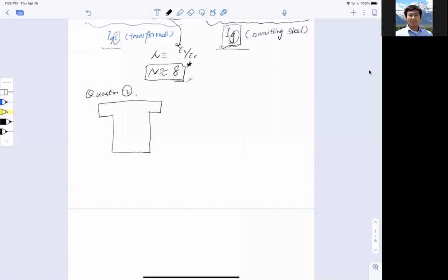So if I want to find out I_cr positive, how do I do that? When you're trying to find I_cr positive and you have steel reinforcement, first of all you have to convert that steel reinforcement into concrete. And knowing that the bottom part is cracked, the neutral axis is somewhere here or somewhere here, it doesn't really matter.